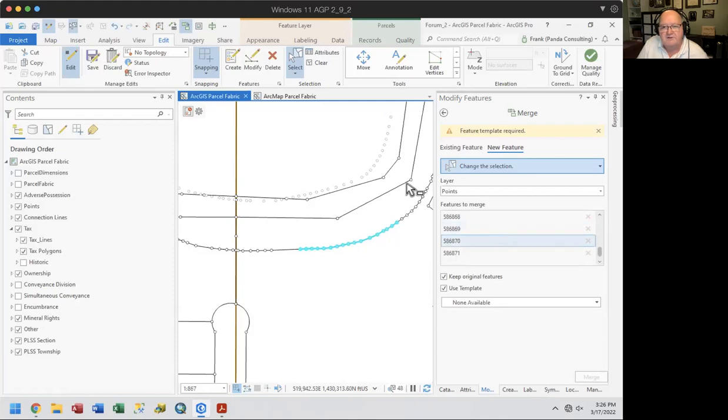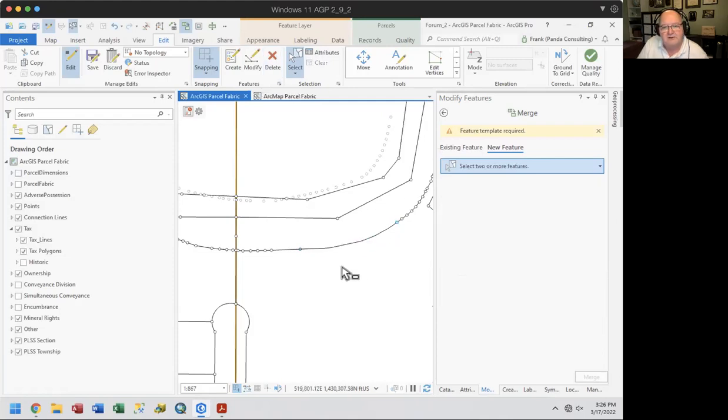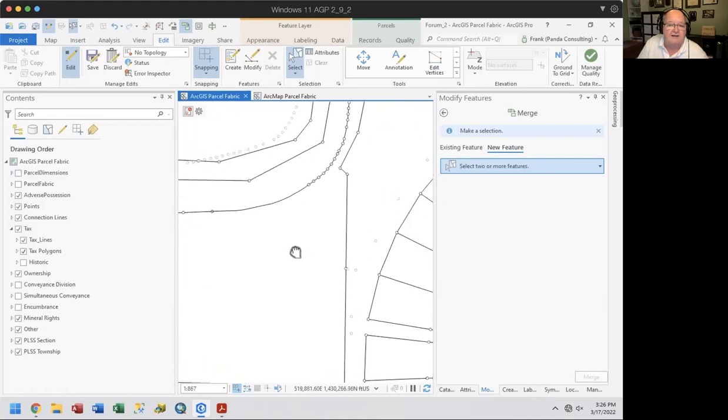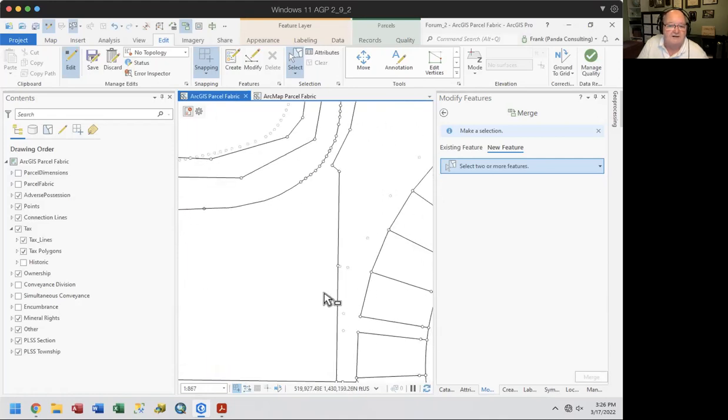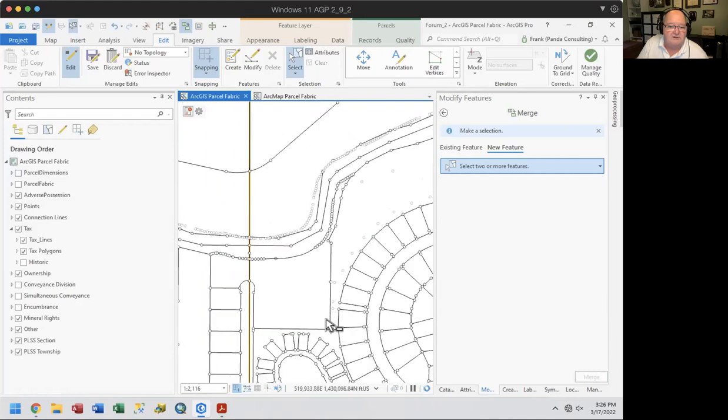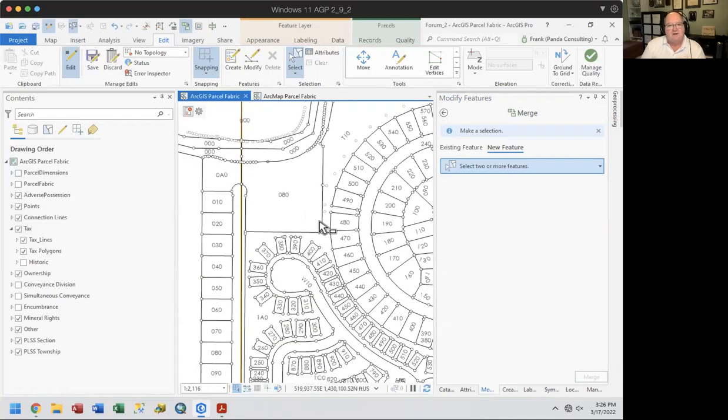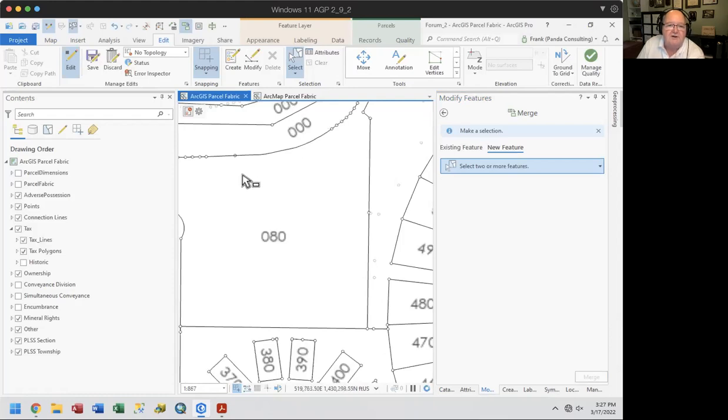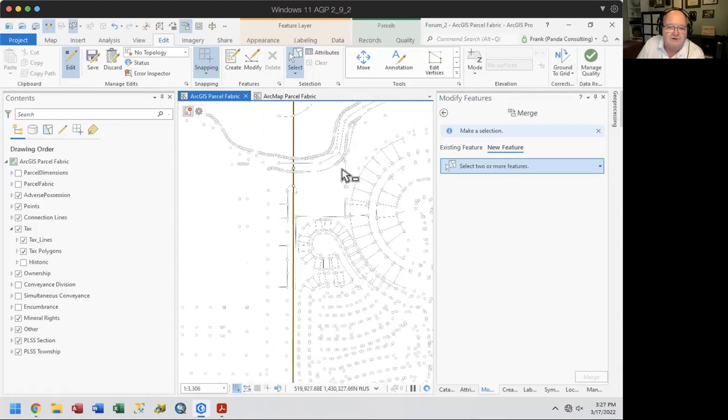And these are all points. And I don't want to merge those points. I want to delete those points out of here. And you can see that I can still have a polyline defined as my boundary instead of just individual discrete lines, which greatly reduces the load and the amount of features that are stored in the database, not just on the geodatabase, but also as far as efficiency and display and that sort of thing. You have a lot less points in here, and it's much more efficient in what you're using.